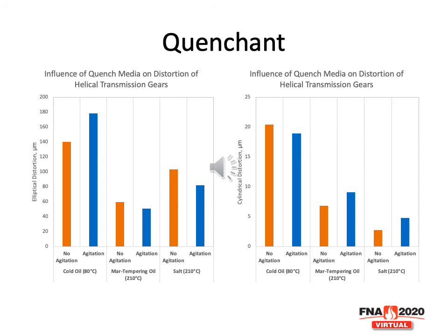Different types of quenchants can influence the distortion that you're going to see, depending on the agitation and depending upon the part or the tempering. Is it, for instance, the cold oils? In this study, the agitated part showed greater distortion than no agitation. And this could be due not so much to agitation as to the non-uniformity of heat transfer around the surface of the part.